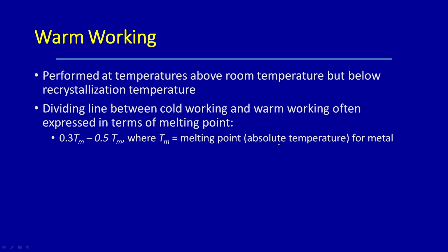And warm working is basically nothing but temperature between 0.3 to 0.5 Tm. That's what it is. Sometimes it is useful because here energy consumption is less, and metals will not oxidize much at lower temperatures, but again it requires machining.